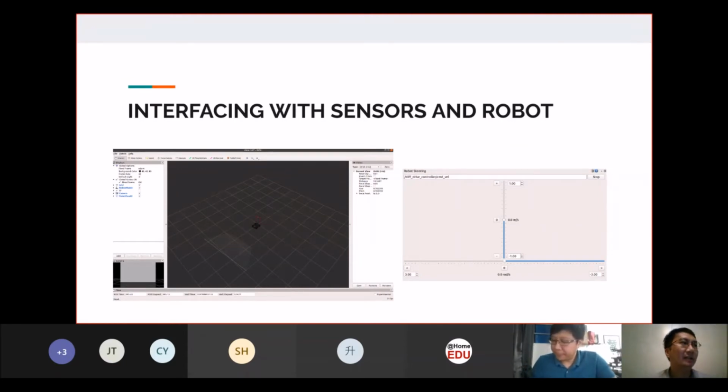Just now you were talking about how we create the URDF and also some definitions to define the functionality, right? So we have a link, we have a joint, and then we have sensors, right? Maybe you want to talk a little bit about the shapes too. If we just want to do things in ROS, we actually don't really care about the shape itself. We just need to know the geometry, right? Yes, we know all the points.